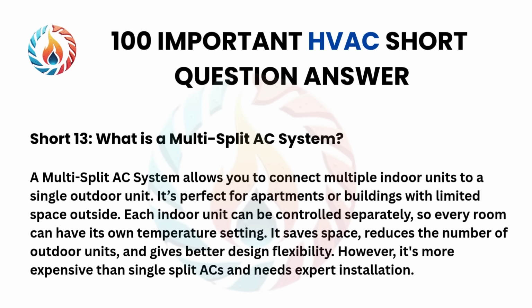Short 13. What is a multi-split AC system? A multi-split AC system allows you to connect multiple indoor units to a single outdoor unit. It's perfect for apartments or buildings with limited space outside. Each indoor unit can be controlled separately, so every room can have its own temperature setting. It saves space, reduces the number of outdoor units, and gives better design flexibility. However, it's more expensive than single-split ACs and needs expert installation.